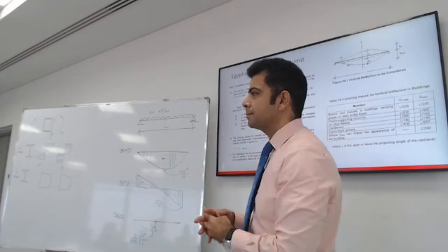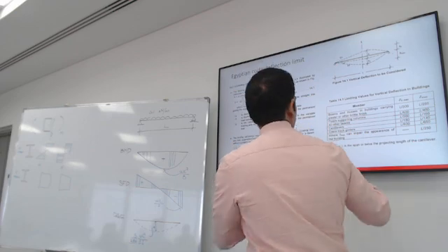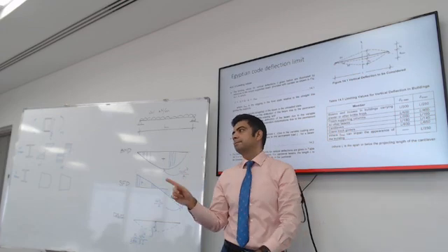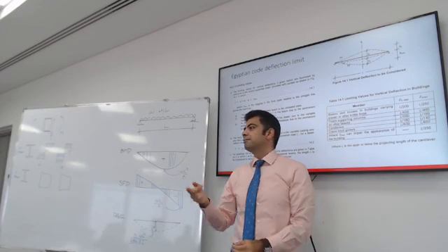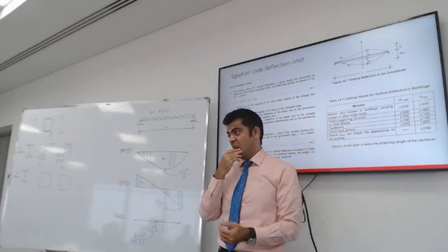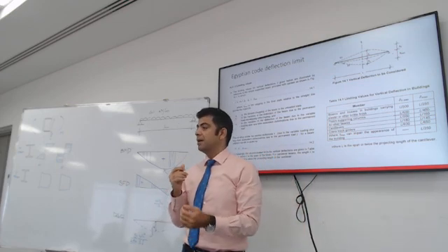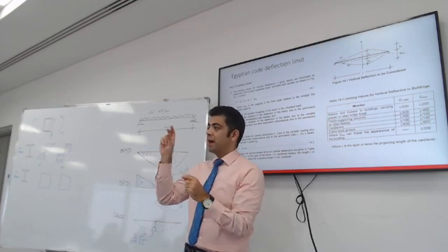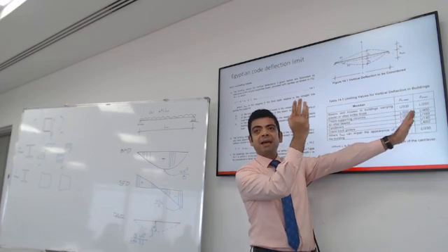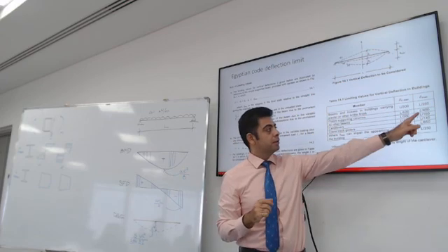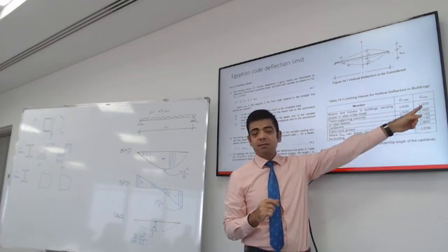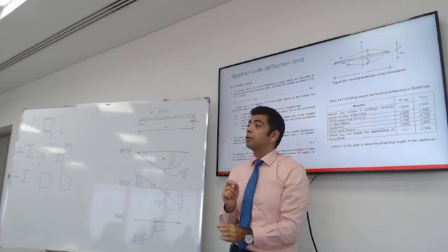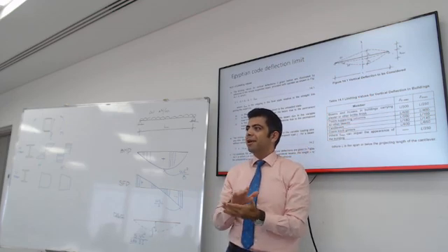The first column is dead load alone, right? This column is the maximum limit for live load only. The next one is dead plus live. So shouldn't I take the dead load and check against this one, then take live plus dead together and check against the other? No, the other way around. You get dead plus live, and you check against the right hand column, which is 250. Yes, that's dead plus live. The left hand column is just for live load. Just the deflection under live load.